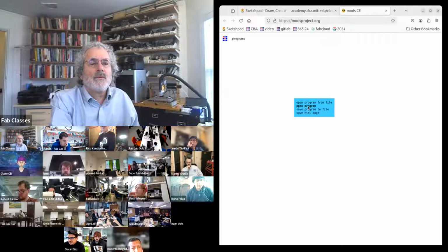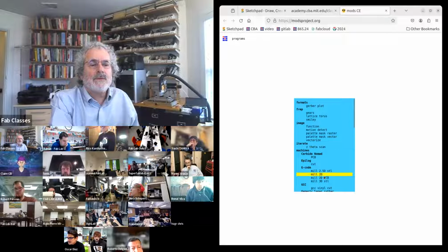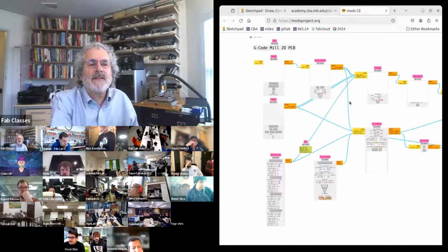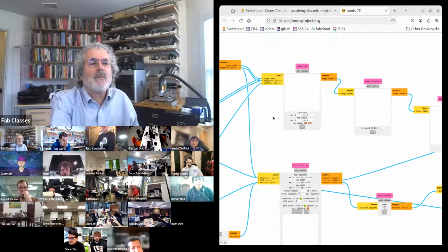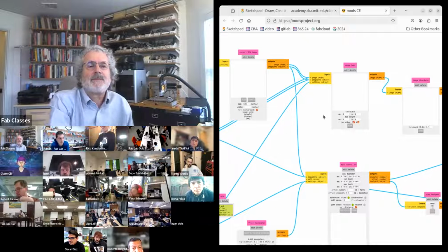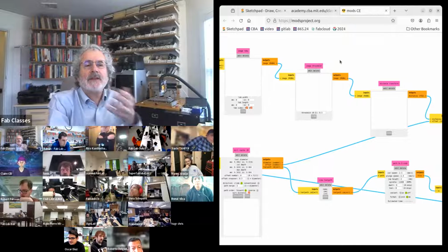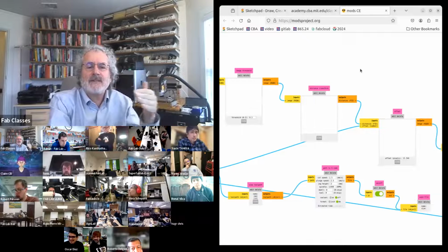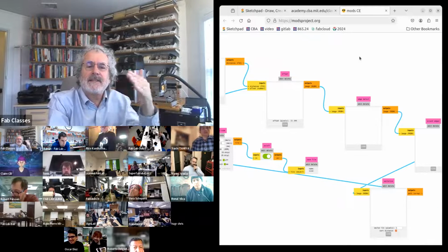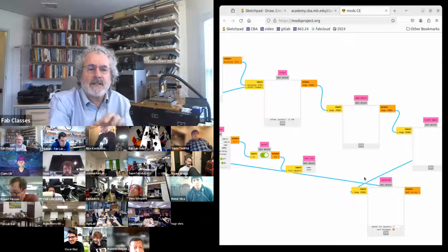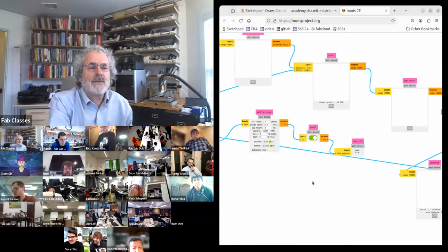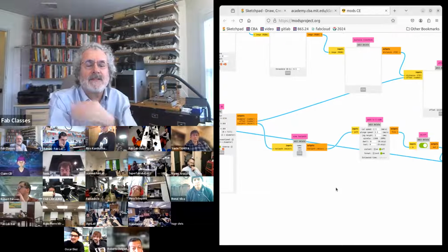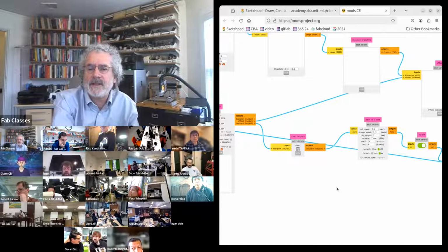If you've been using mods, you probably haven't looked at the details, but when you bring in an image, this thresholds it. This finds the distance to the edges. This offsets for the tool size. This finds the edges. This orients the direction. This turns them into strokes. And this accumulates them into the tool path. And then this converts that into what the machine can understand.